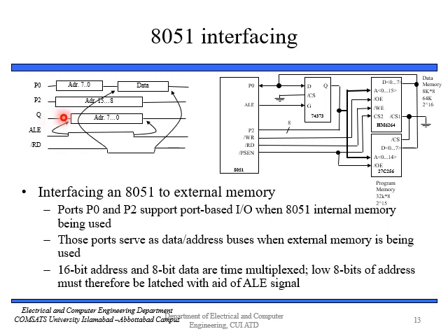For that we are using this address latch enable. When address latch enable is enabled, we hold this address, that is from 0 to 7, and then we combine this address with the other address, and finally our read signal will assert and we read the data. So 16-bit address and 8-bit data are multiplexed.